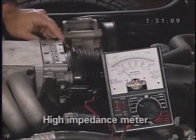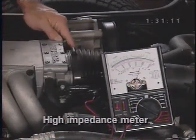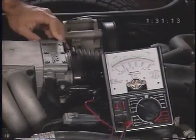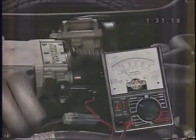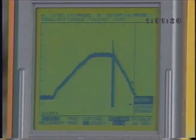One way to test a potentiometer is with an analog voltmeter, but the needle response is often too slow to show a glitch in the voltage. Scopemeter's 50 megahertz bandwidth and 40 nanosecond glitch capture make it the perfect tool for viewing and diagnosing potentiometers. Here's how.